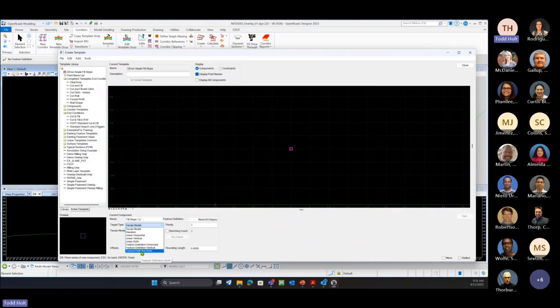We can also specify a certain feature definition, so maybe it's right of way, a wall, a match line, or some other condition that we want it to solve for. We're going to build into that end condition to search for that particular target. Later on we'll do the feature definitions for right of way, but for the first example, we're just going to set our terrain model.